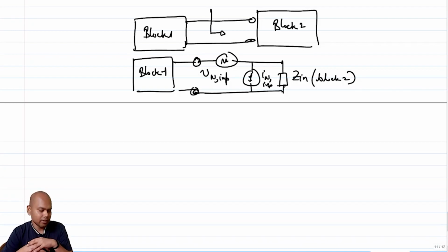The reason those are more effective is because generally at lower frequencies the Zin is almost infinite, and RS is much smaller than Zin. So essentially you can assume the equivalent case is RS equal to 0.